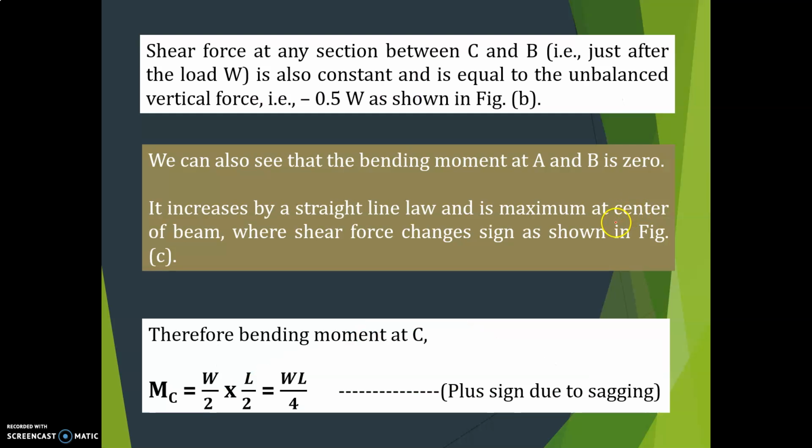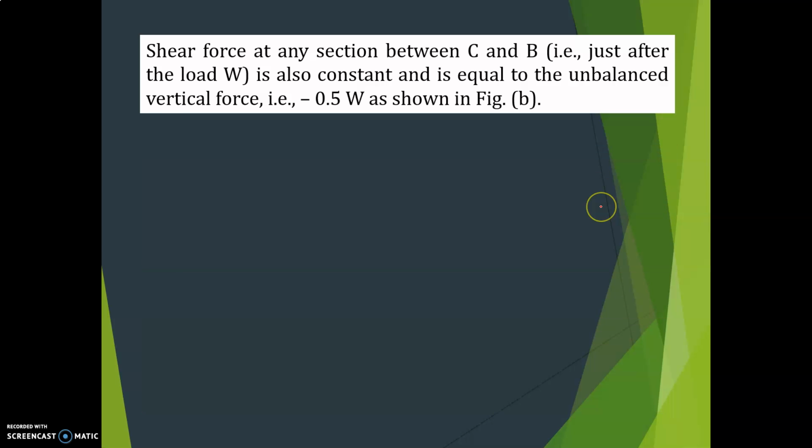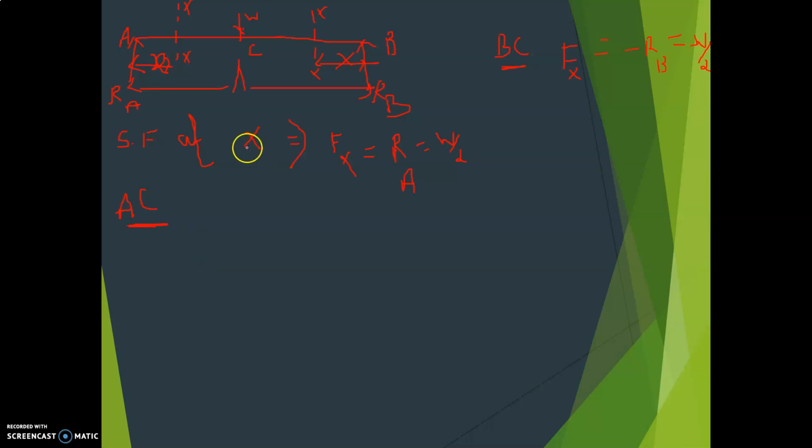Okay, how can you calculate bending moment? Again consider the same section. I'll consider the same section here, at this point only. Now this was about shear force. I'll consider now bending moment at X. What is that? Bending moment at X, that is equal to Mx. That is given by force into perpendicular distance to the left or right of the section.